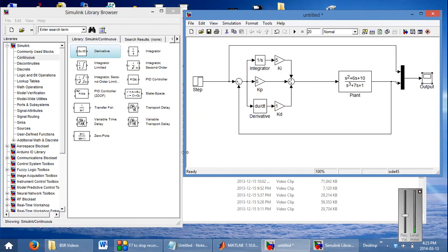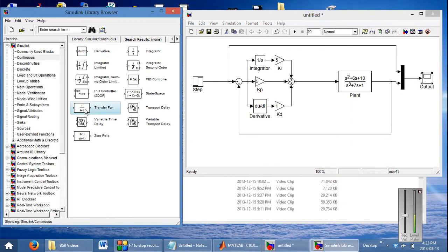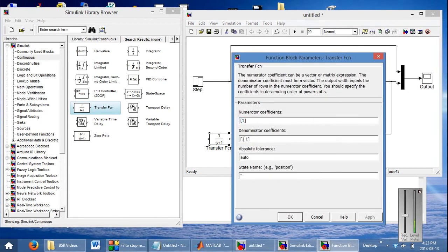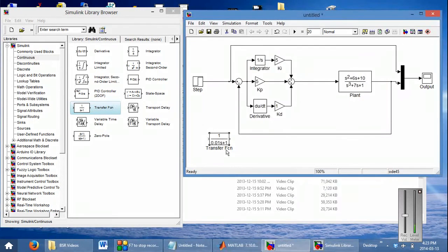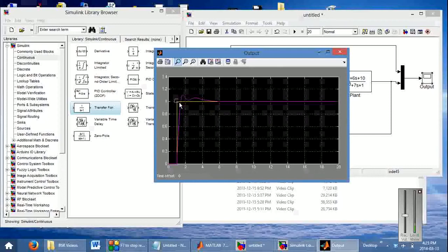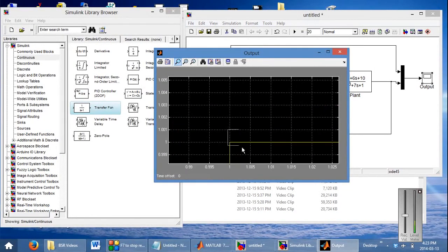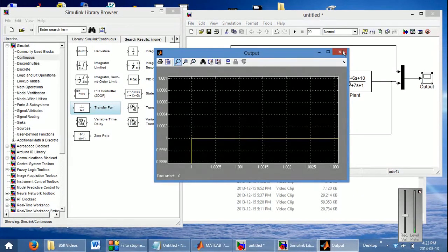The way you can address this is by adding a transfer function to your input. The whole purpose of this transfer function is going to be to filter the signal. So if we add the following transfer function in series with your input, let's run the system. Your yellow is your input, and you'll find that it's exactly just like a corner.